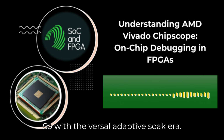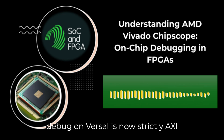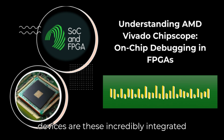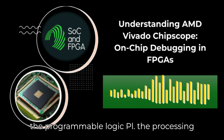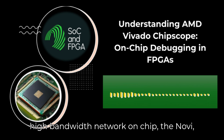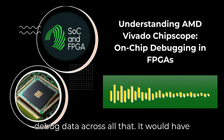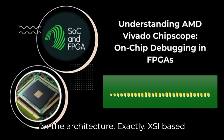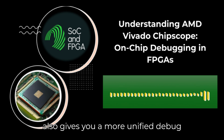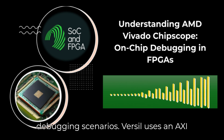So with the Versal Adaptive SoC era, there was a fundamental redesign. On-chip debug on Versal is now strictly AXI-based. AXI-based. Why the change? The rationale is pretty simple. Versal devices are these incredibly integrated, heterogeneous platforms, right? You've got the programmable logic, PL, the processing system, PS, with ARM cores, AI engines, AIE, all connected by a super high bandwidth network on chip, the NoC. Okay. A slow JTAG chain trying to pull debug data across all that would have been a massive bottleneck. Right. Too slow for the architecture. Exactly. AXI-based debug offers much higher bandwidth for reading those trace buffers back. It also gives you a more unified debug methodology across the PS and the PL, and it provides far better support for remote debugging scenarios.